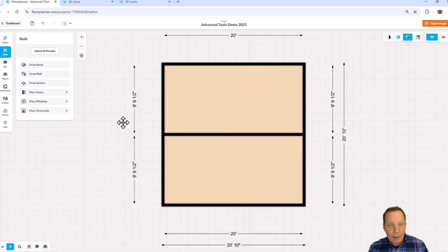It happened automatically because at any point that you drag in from adjoining to the structure over here on the left-hand side, the new wall will acquire the height at the point you started, as we did here at the 14 feet. That's why it is actually a 14-foot high wall. You know it's 14 feet high there. You know it's 10 feet high down here. Yet if I wanted to build a small closet down here in the corner and have it touch the ceiling, I would never know what the height is at this point. Somewhere between 10 and 14 feet or somewhere up here. So an advantage to be able to drag in from outside and acquire that height.